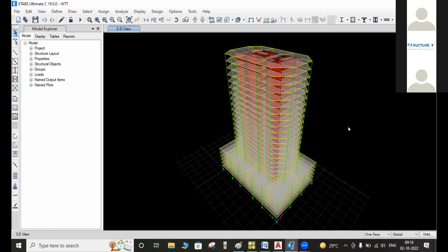That is a linear dynamic analysis, right, Karim? Yes. So it is part of linear dynamic analysis, and this is free vibration. This is a kind of checking the building configuration based on the self weight, with the time period and frequencies, right? In this one, we are going to check the mode shapes, right, Karim? There are three motives for doing this modal analysis. We have to check the time period, the frequency, and the mass participation ratio, like how much mass is participating in the first mode, second mode, and third mode, right? This is based on linear dynamics.